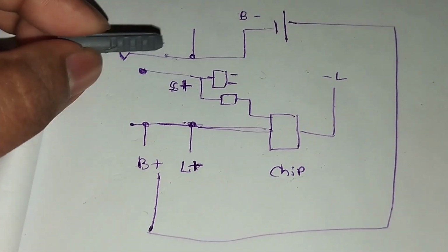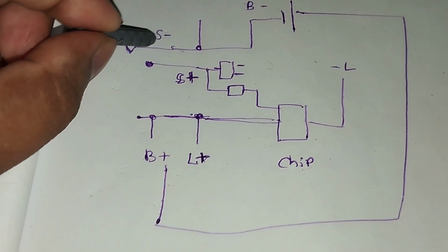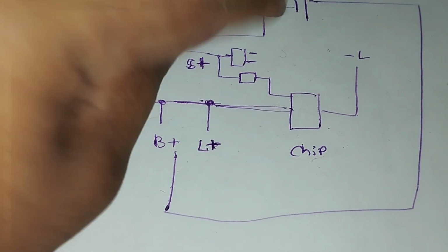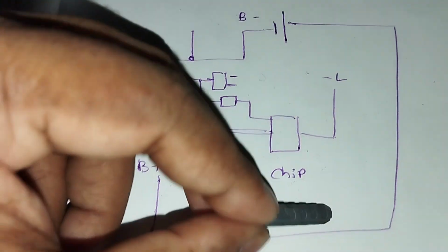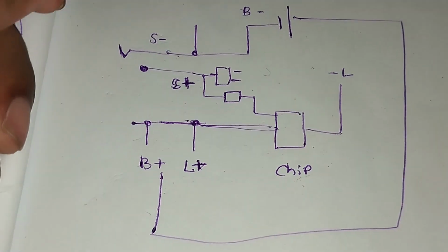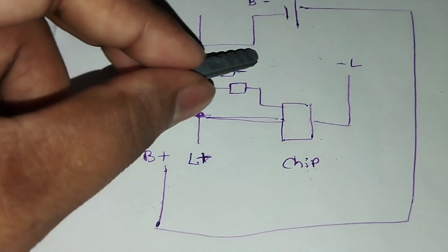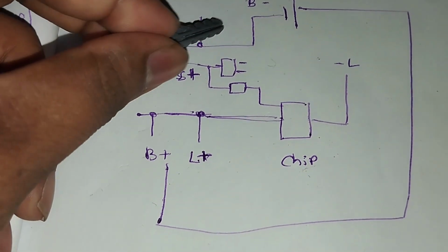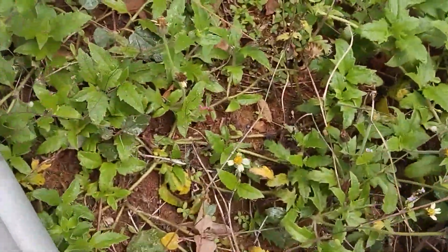There are no diodes or anything to protect from polarization, so no reverse polarity protection or voltage protection. Imagine what might happen to the solar panel. I don't know about short circuits of the solar panel from this to this, but that could happen because we have a lot of external wires. That's the base diagram.